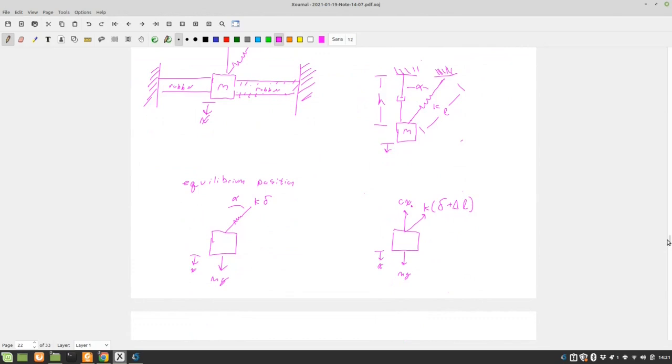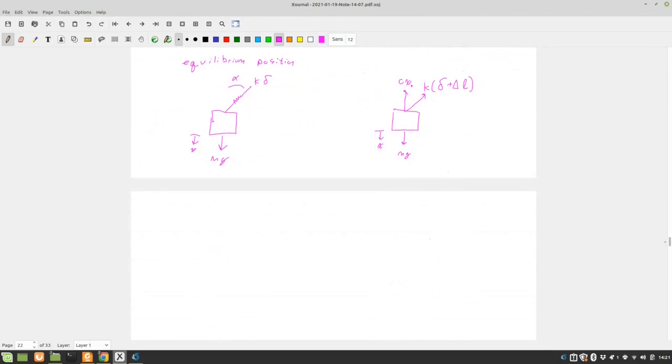Yeah, it does. So first thing we need to do is do our Hooke's law. So positive down, the sum of forces in the x is equal to mg minus k delta cosine of alpha is equal to 0. That makes sense? The sum of forces in our x, so we're just worried about this x component of our spring. Okay?